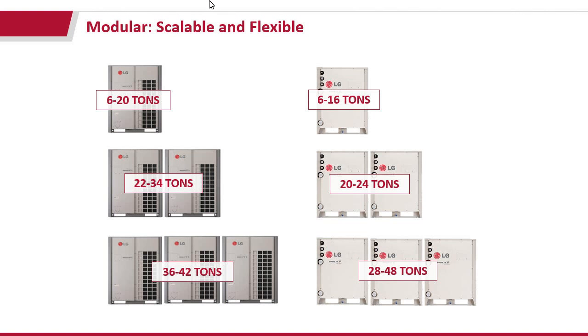So you can get whatever you need out of the equipment that you have, and this is across the board from the manufacturers. The tonnage might not be exactly equal, but this technology is modular like this. And when you do have these combined systems, note that the controls are integrated such that they operate as one unit, and you don't have to worry about any complicated sequence of operation to say, oh, lead lag this one. You don't have to worry about that. It's going to take care of itself within the controls it comes with.